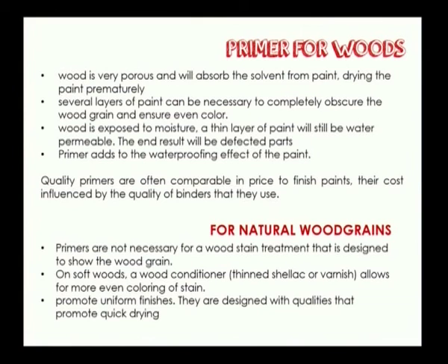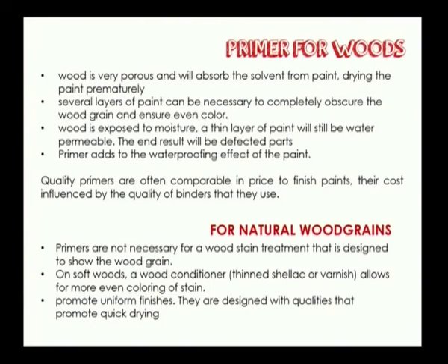On soft woods, a wood conditioner like thin shellac or varnish allows for more even coloring of the stain. Now, this promotes uniform finishes and they are designed with qualities that promote quick drying as well. So, you saw for woods, in case you are using varnishes, you do not need paints. Using a stain treatment, you do not need primer, but when you are using opaque protective coatings for woods, you definitely need a primer before you coat it with a final coat.